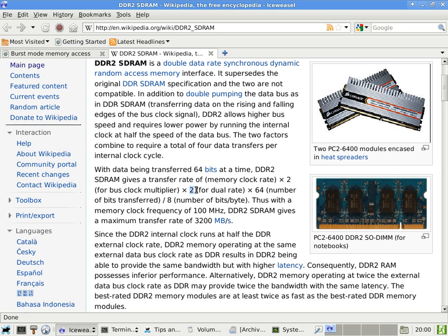Without using DDR2, this is one sample time. So let's say on every falling edge you can sample. This is one falling edge, this is one falling edge, and so on. But if the memory is capable of sampling also on the rising edge, now you have suddenly just doubled the amount of transfer that is possible per unit of time, without changing the actual underlying clock speed.